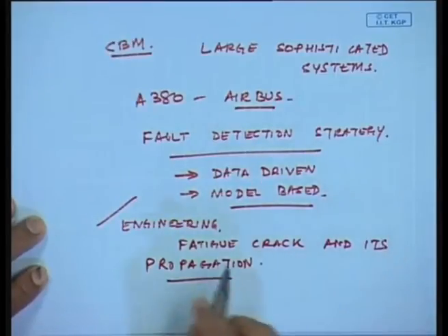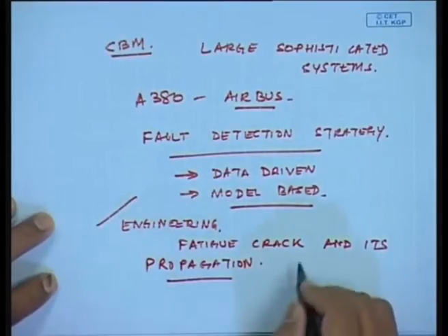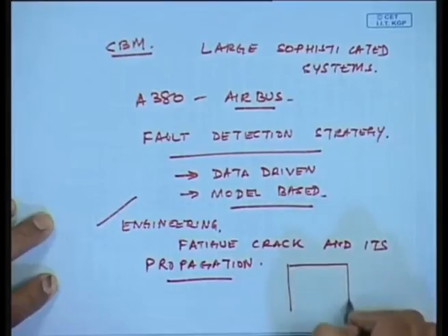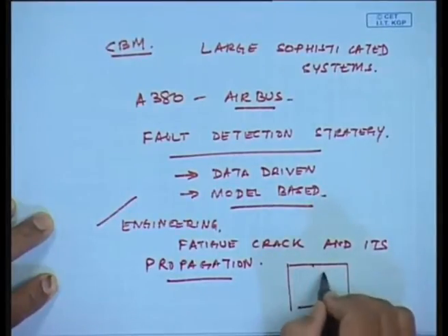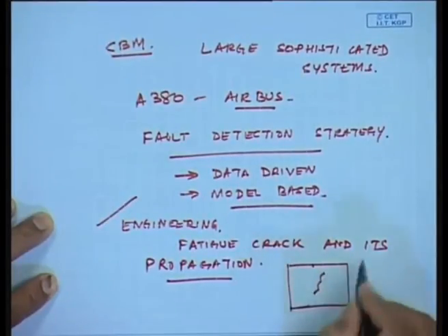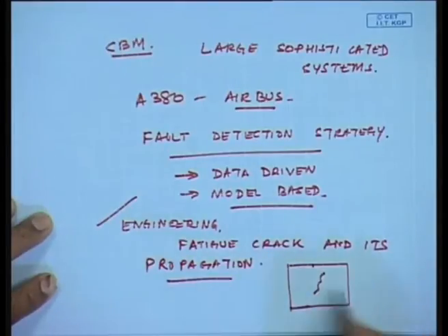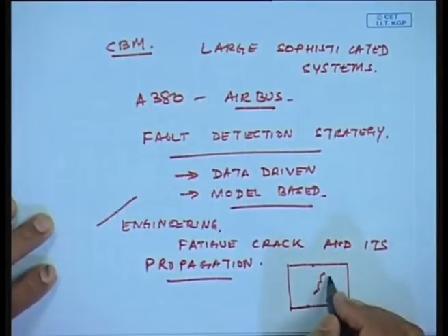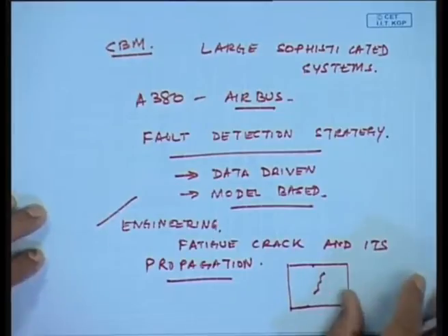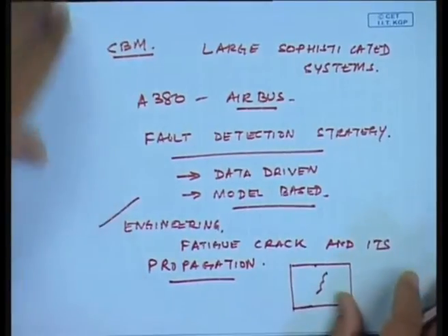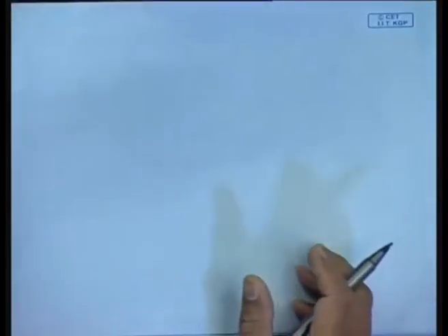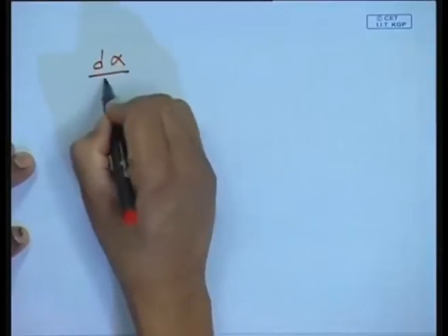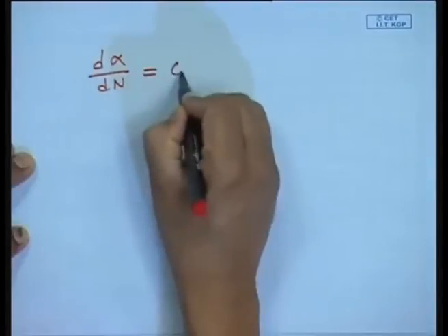So once a crack has developed on a machinery component, say some crack on a machine component, the next question people always have in their mind is, how long is this crack going to be there? Can my machine still run under this crack condition, etc.? And the most important equation to this is the crack growth parameter with the number of cycles of operation.